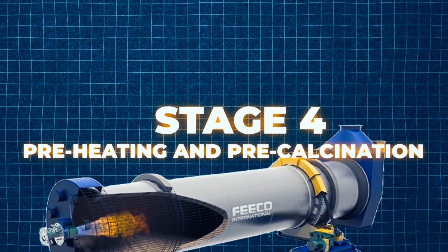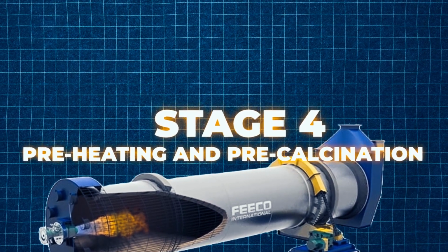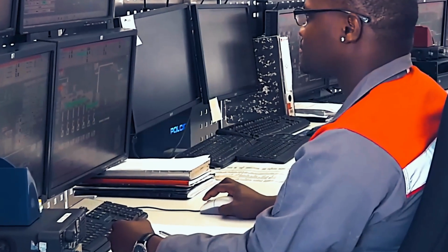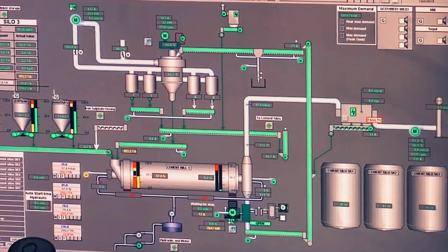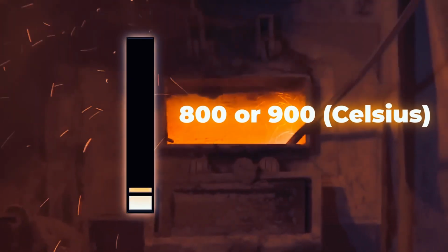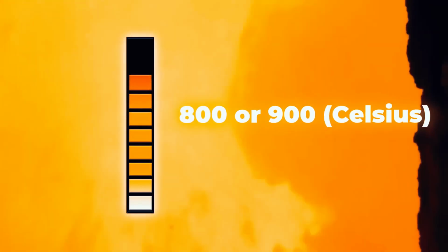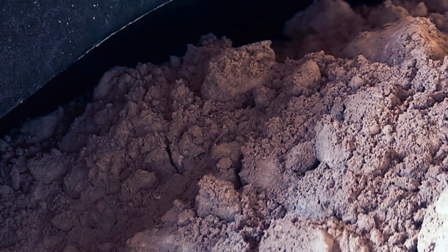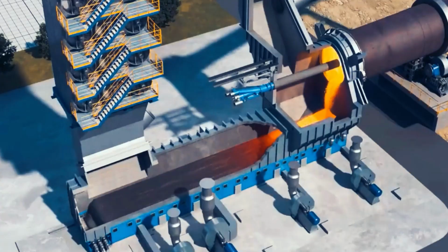Stage 4. Preheating and precalcination. The raw mix preparation process is then followed by preheating and precalcining the raw mix to make the process use less fuel and make more. The raw materials are heated to 800 to 900 degrees Celsius in a machine such as a tower preheater or a vortex preheater. During this step, any water or carbon dioxide is taken out of the mix. Some of the chemical reactions that are needed to make cement start with this step.